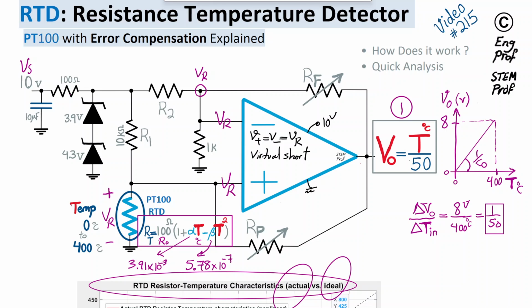Okay, now the next move is also talking about the bias of the circuit via a 10-volt supply voltage, via 100 ohm. Even if the supply changes by plus or minus 1 volt, we are providing a minimum of 8 milliamp bias current to this combination of Zener diodes.